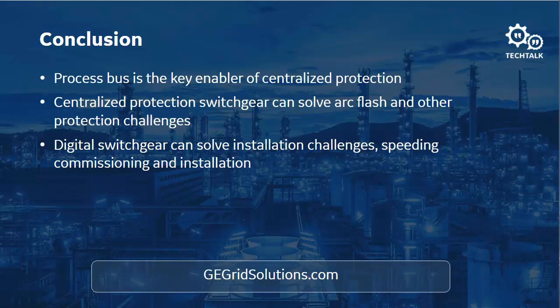Now, the other piece to this too is that at the distribution level, where we're talking about medium voltage distribution, we've never had any sort of redundancy before. And we can very easily achieve, at the cost of just another relay, redundancy with one more relay. If we had to have redundancy on a bus that had 10 breakers on it, it would cost us 20 relays versus 10. This would cost us 2 relays versus 1 to have redundancy.